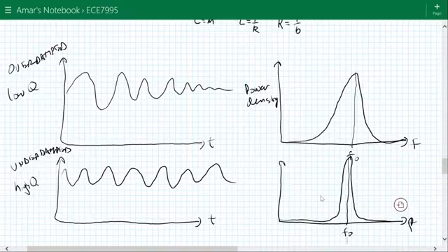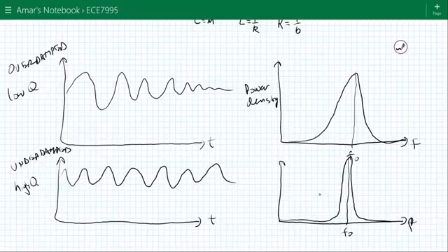This makes it easier to measure the resonant frequency. There are fewer energy losses in the system, and it turns out the system is much more accurate. So the quality factor has to do with the height of the peak divided by the width of the peak. The larger the height of the peak and the smaller the width of the peak, the higher the quality factor.